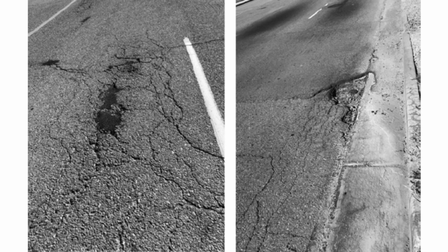Causes: infiltration of moisture and poor drainage of moisture are the primary causes of stripping. Treatments: repairs in both the asphalt layer and the underlying base subgrade are required. Thus, full-depth reclamation is the only remedy for stripping. Stripping may be avoided with a proper drainage system and by sealing cracks regularly.